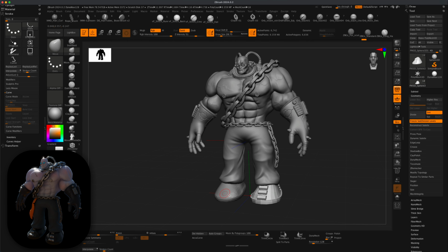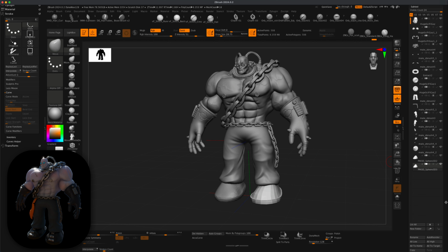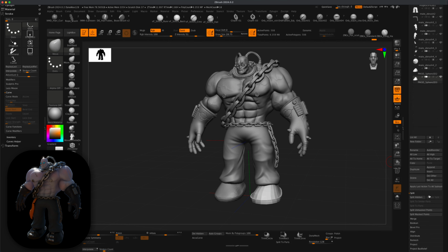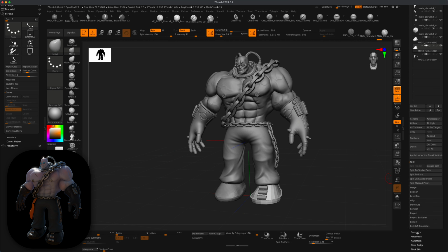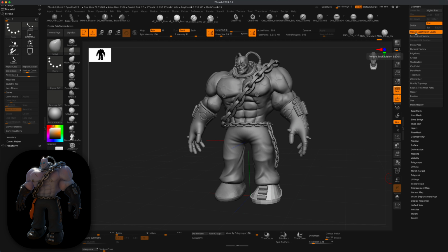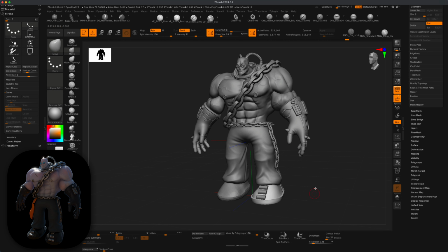All right, and to copy my shoe to the other side, I'm going to auto group it, do Control Shift click to hide all the separate pieces. And now, as we've done before, let's go to subtool, and let's do a split, and we'll do split hidden, and that's going to put these pieces on its own layer, right? Which means we can go to geometry, and let's jump out of freeze subdivision, right? And that's going to give us our shoe back. Now we have something like this.